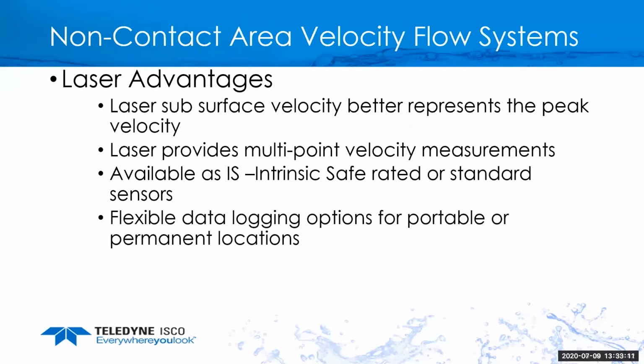A lot of flexibility in data logging now, for both portable and permanent locations. So you need to determine, what do you have for power? What do you need? Do you need a local display? Do you need analog Modbus? Are you going to go to RTU? Are you going to go to SCADA? So you need to look at all those things, but there's a lot more flexibility with logging and meter options these days.